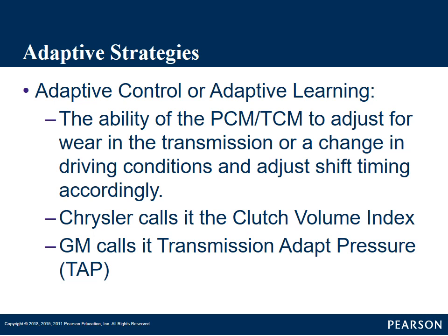As a matter of fact, these adaptives, when we replace transmissions, we relearn those adaptives. We reflash the computer. With a lot of your early Chrysler electronic automatic transmissions, you would repair or replace the computer, and there was a process using the scanner and actually shifting the transmission to reset these clutch volume indexes.